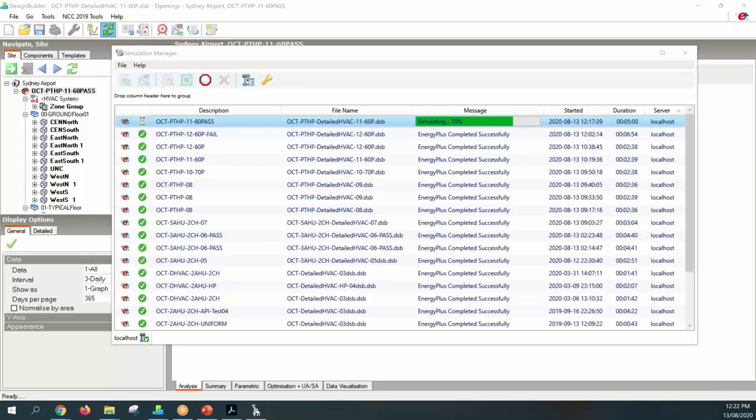So instead, you set back the temperature from 21 degrees to 12 degrees, and then the building cools down to 12 degrees and the heating system kicks back on and keeps it at 12, so that the next day when you come, you're not trying to get it up from minus 10 degrees centigrade. And it's the reverse in very hot climates. Some of the buildings, the air conditioning never gets completely switched off. They just reset the thermostat during outside hours.